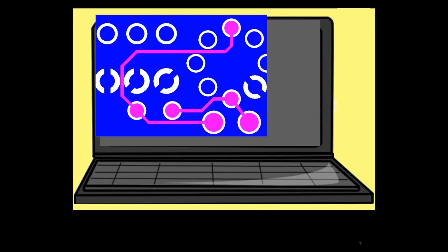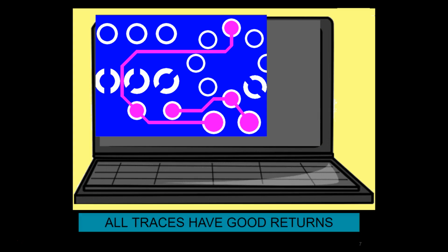The closer together the two layers are, the more noise cancellation is established. This is due to the capacitance that is created. Also, if the trace has a blank area underneath it in the ground plane, then the electrons must travel farther and may interfere with the return path of another signal, and this creates noise.